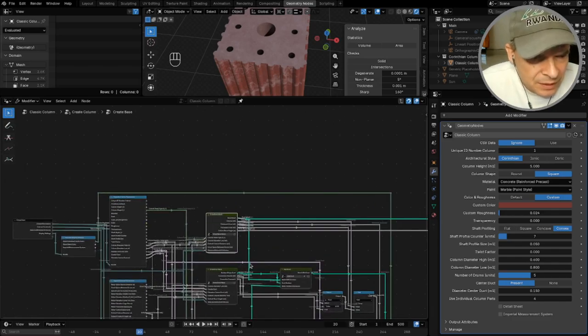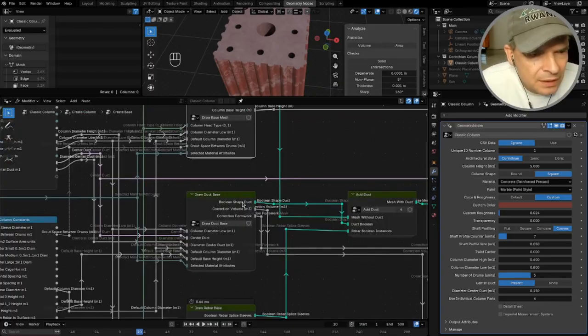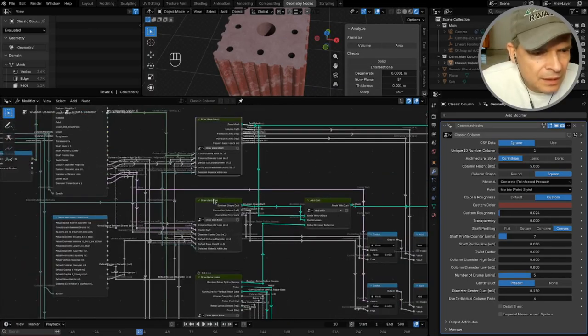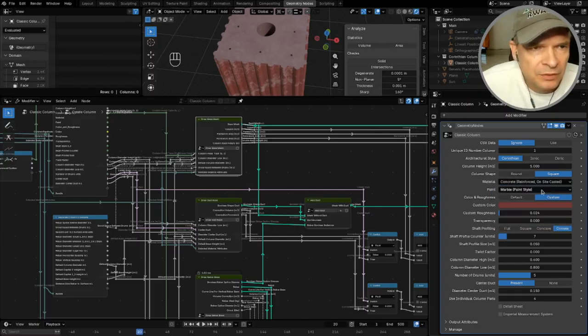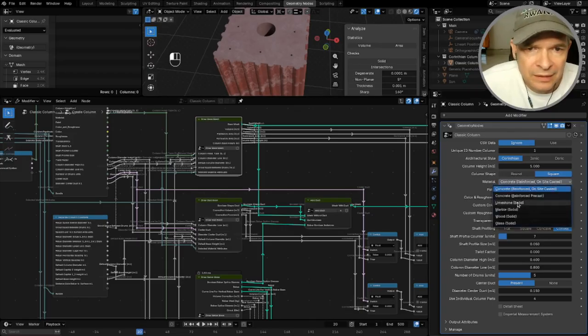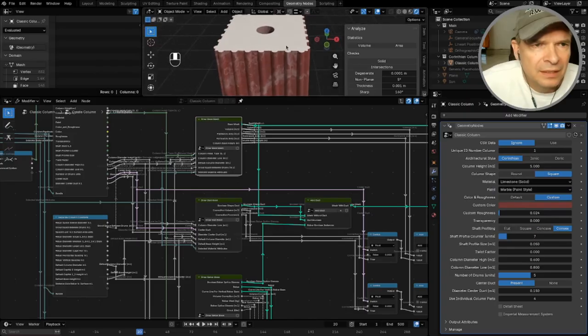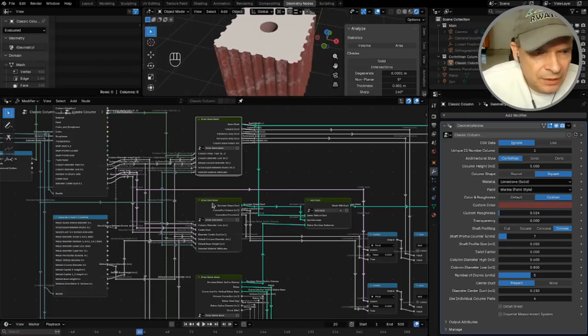Okay, so let me see. Yeah, and each time, which also applies for the column head, we need to draw a duct if it's used, and we need to use the splice sleeves for the rebar if it's reinforced concrete or precast concrete, or we don't if it's just regular concrete, or none if it's like limestone. So that is also done, and that is done here.